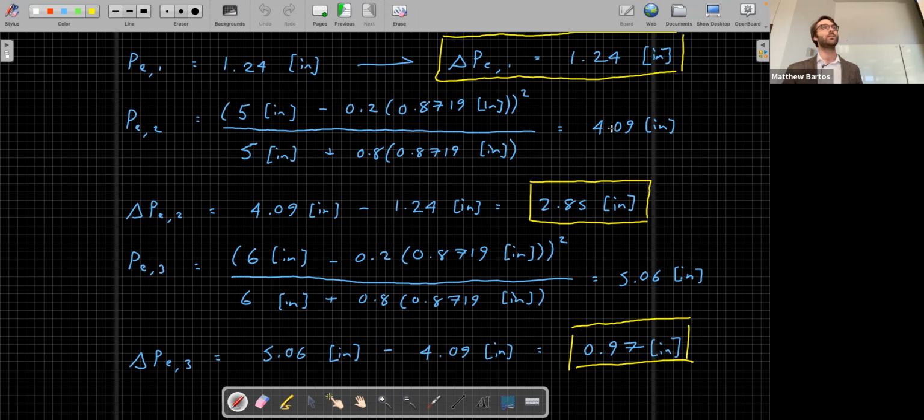To compute the excess precipitation in the second hour, we take the excess precipitation within the first 2 hours and subtract the excess precipitation within the first hour. Similarly, for the entire 3 hours, we plug in the cumulative rainfall over the 3 hours and subtract the excess precipitation from the first 2 hours.